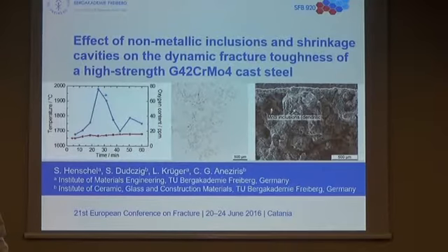So to sum up, in the steel casting simulator, we generated endogenous alumina inclusions, but these alumina inclusions were mainly observed near the crucible wall. And due to the high manganese sulfide content in this batch of the steel, manganese sulfide inclusions were also formed.